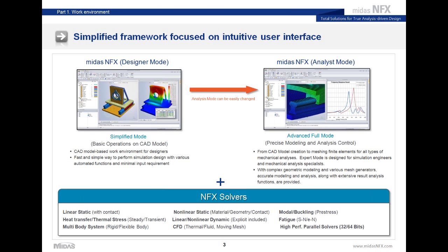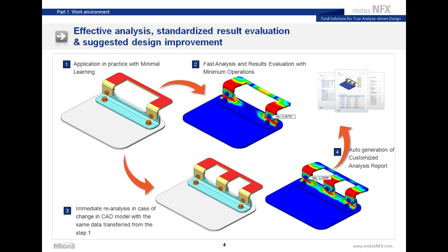So after that, I will talk about the workflow, which is very simple. In fact, in Midas NFX, first you have to import a CAD model. Then you apply some boundary conditions, some loads, you create an analysis case, and you obtain some results.